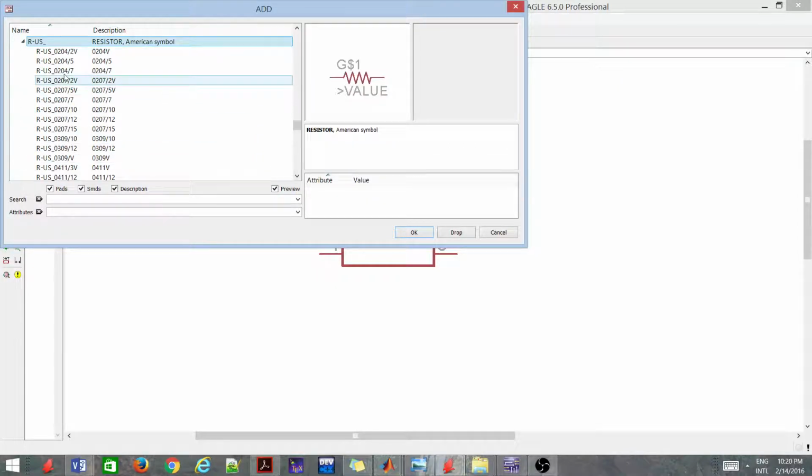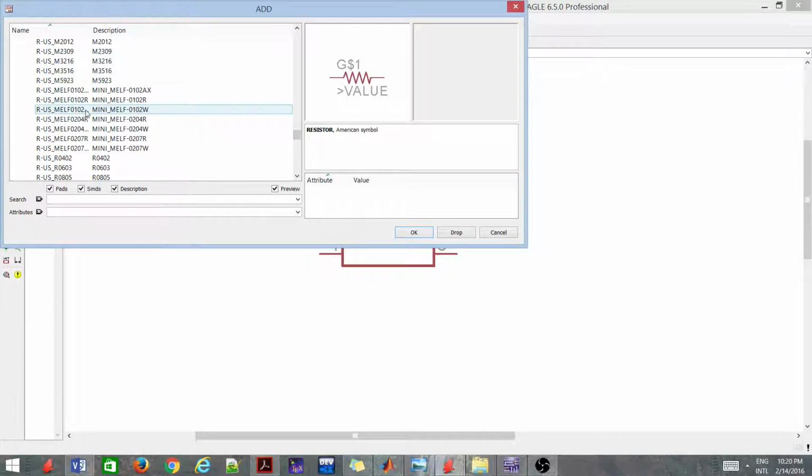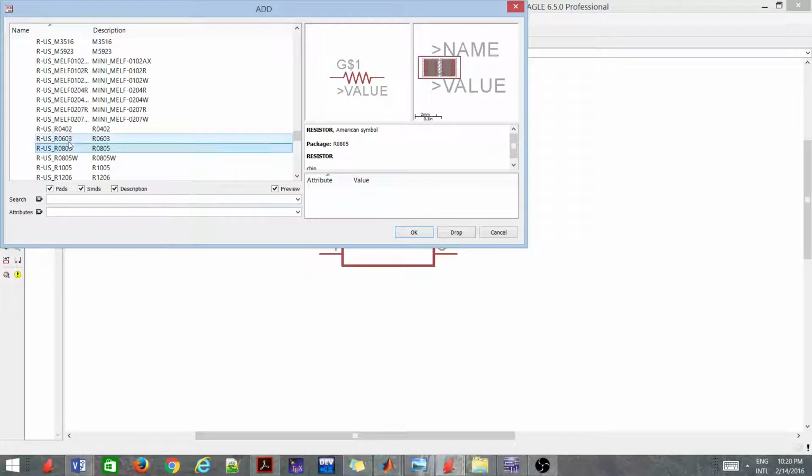Now what I'll do is I'll cover an SMD package this time for a better feel of how you can design, so that if I take an SMD and this IC is a DIP, you get a feel of how you connect SMD with DIP. Generally for SMD we either take 0805 or 0603.